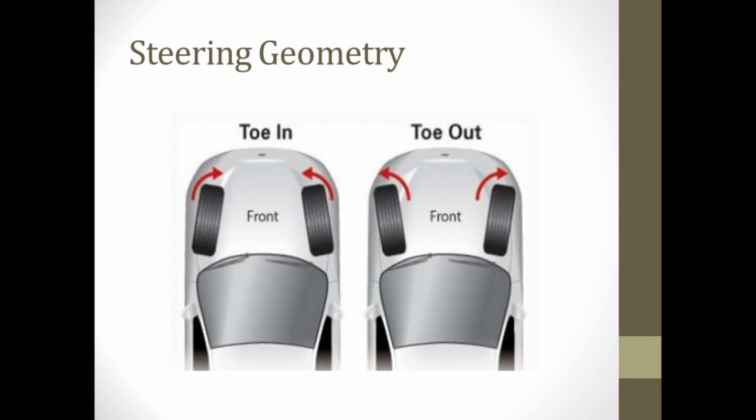In automotive engineering, toe is also known as tracking. This can be contrasted with steer, which is the anti-symmetric angle, where both wheels point to the left or right in parallel. Positive toe or toe in is the front of wheel pointing towards the center line of the vehicle. Negative toe or toe out is the front of the wheel pointing away from the center line of the vehicle.